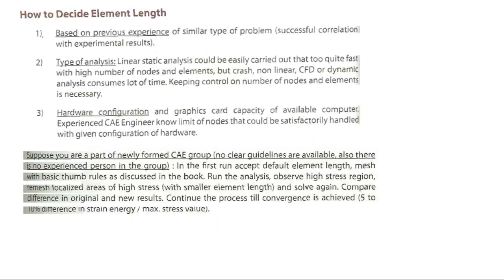How to decide element length: based on previous experience of similar types of problems, successful correlation with experimental results, and the type of analysis we are going to use. A linear static analysis could be carried out quite fast with a high number of nodes and elements, but crash, nonlinear, CFD, and dynamic analysis consume a lot of time.